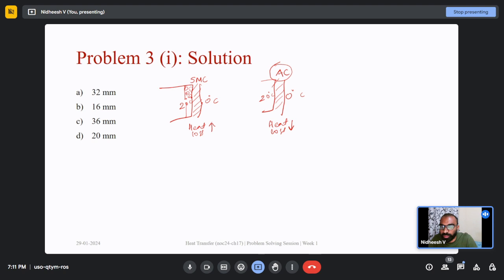Say this is polystyrene sheet material. We are going to add that, so that the combined resistance to heat flow is equivalent to that of aerated concrete. Is that clear? Yes, sir. Okay. Now we want to find out what would be the thickness of this extra polystyrene sheet that we should add to stone mix concrete, so that their combined effect would be equivalent to that of aerated concrete.